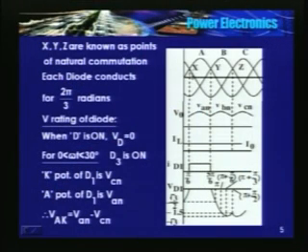At point X, you will find that phase A becomes more positive than phase C. So this is phase C, this is phase A, and this is phase B. Phase A cuts 0 and becomes positive; after 120 degrees phase B, and after 120 degrees phase C. So at point X, the instantaneous value of the phase C voltage is the same as the instantaneous value of the phase A voltage, and beyond point X, phase A becomes more positive.